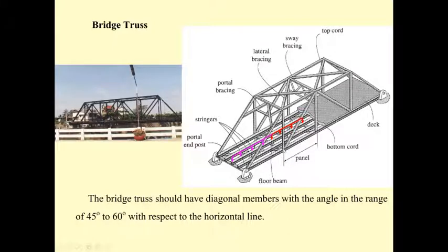And since this joint, and this joint, 3 of these joints are going to receive the same kind of reaction from the floor beam, because each is going to take the same area of the deck. And you may see that the support here will be subjected to the force transferred from the floor beam also, but it's going to be half of the inside floor beam. Okay, this is the general idea of this.